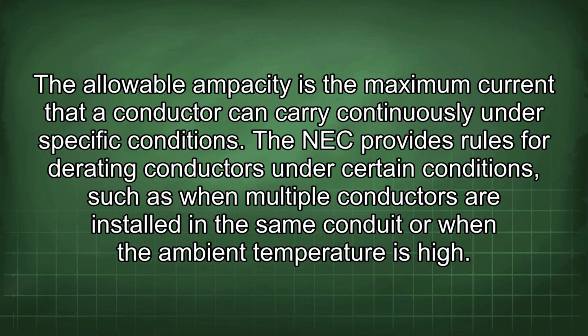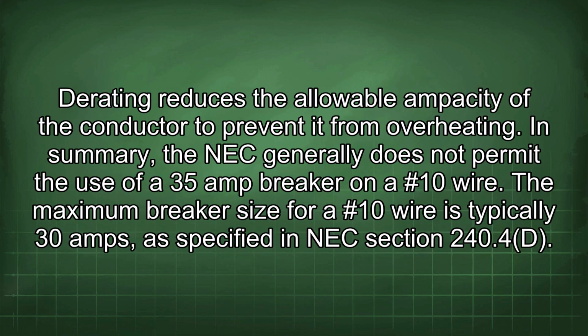The NEC provides rules for derating conductors under certain conditions, such as when multiple conductors are installed in the same conduit or when the ambient temperature is high. Derating reduces the allowable ampacity of the conductor to prevent it from overheating.